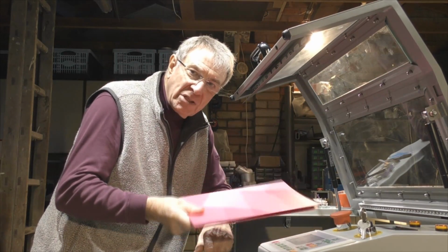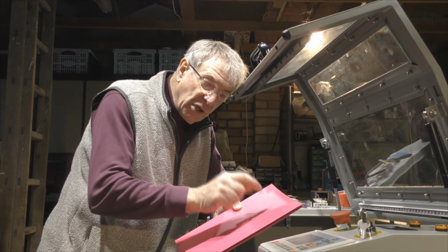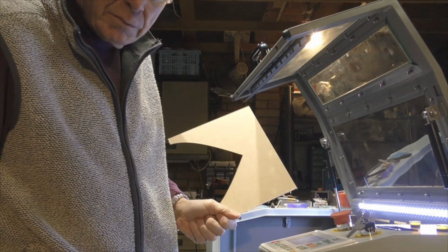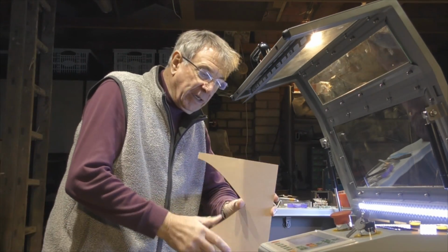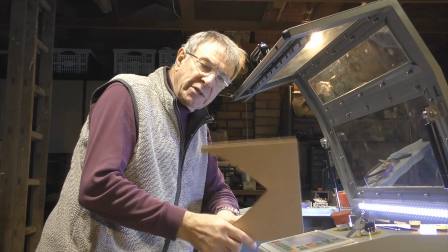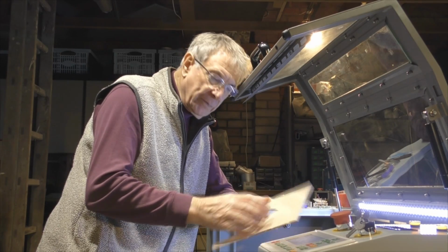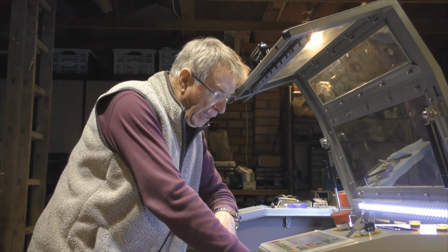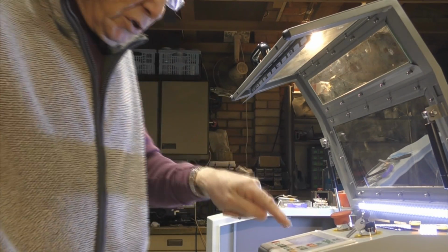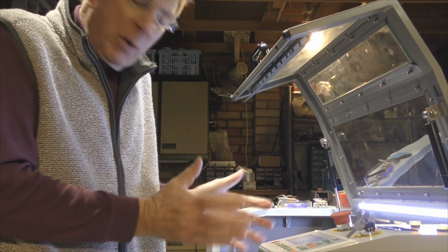We're not going to spend too much time initially filling in this sheet. What we're trying to do is quickly get to the parameters that we can record in here as being the correct recipe. The first thing we need to do is choose a material. And we're going to start off with something nice and simple. Here I've got a piece of 1/8, 3.125 hardboard. It's a high density fibre board. So the next thing you'll need to do, I would recommend that you get yourself a program built into your machine here, which is a 40mm square or a 50mm square, something small and compact like that.